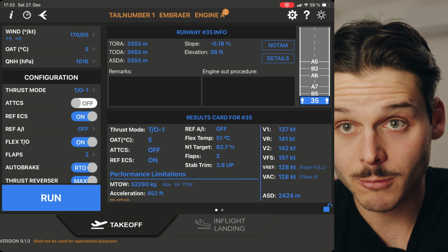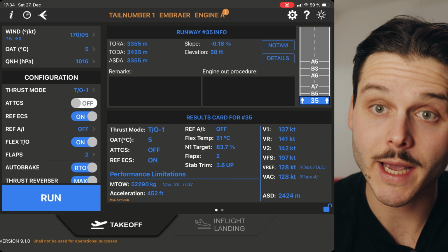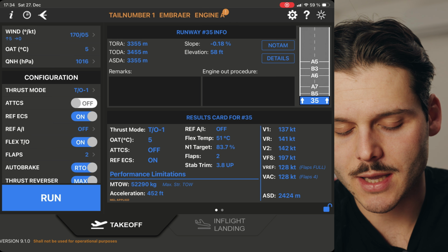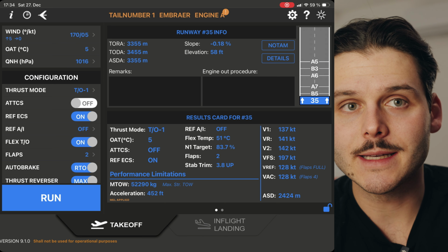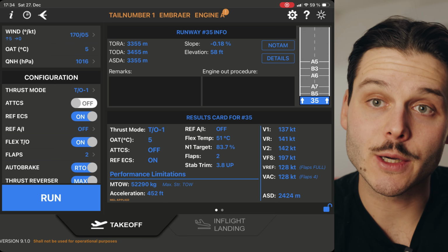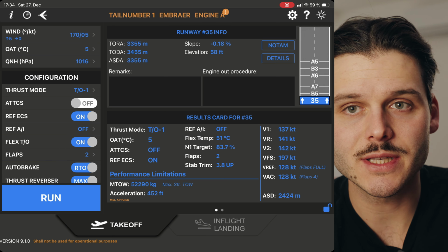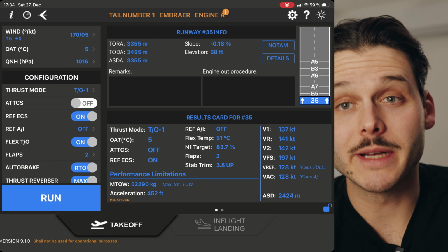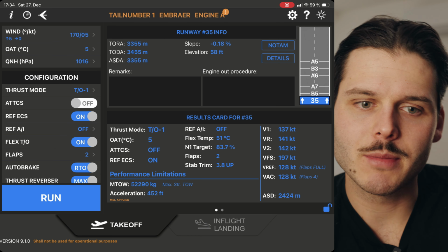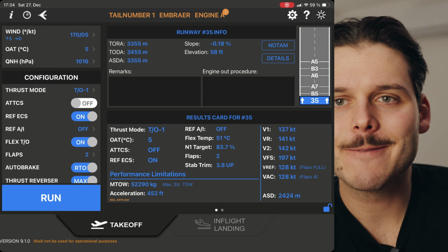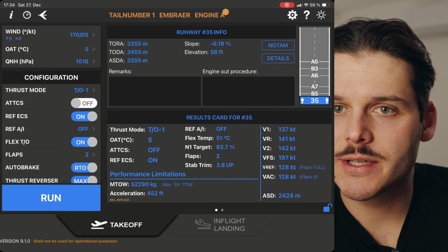And then on top of the derate, which you actually call derate on a Boeing aircraft, you have the flex temperature that you can additionally put into that. The whole reason for that is to even more reduce the takeoff thrust, even more decrease engine wear. It actually does not decrease fuel consumption, but it decreases engine wear and noise. And noise is a big thing for aircraft, because we do pay landing fees depending on how noisy our aircraft is.